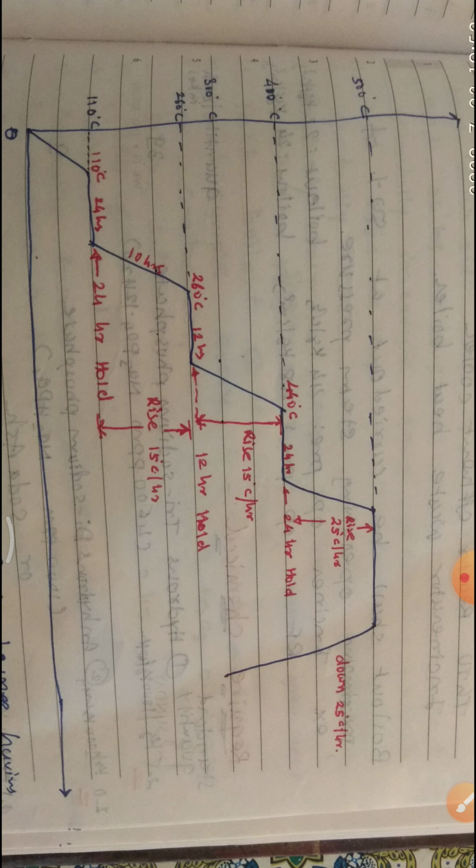After the 12-hour hold finishes, start increasing the temperature at 15 degrees centigrade per hour and reach 440 degrees centigrade and hold for 24 hours.